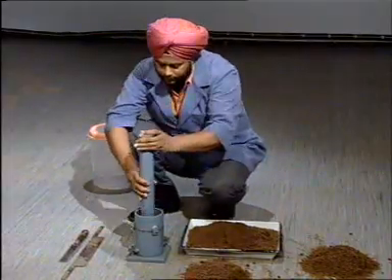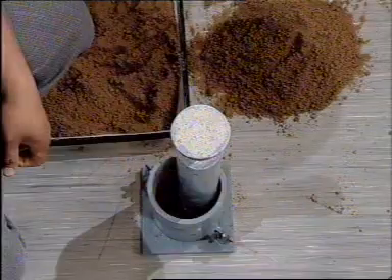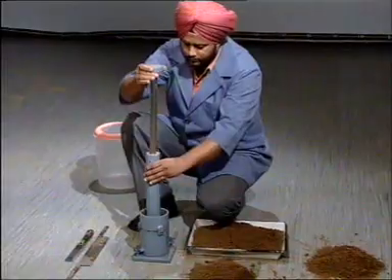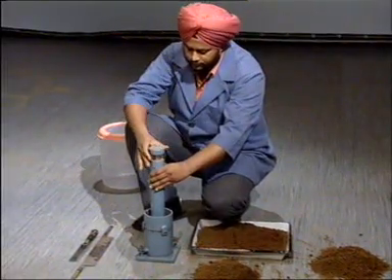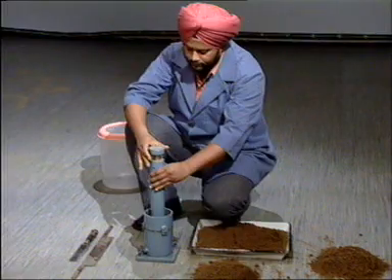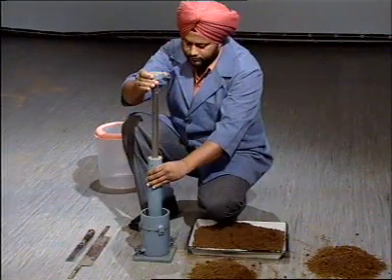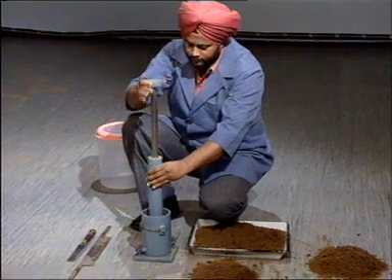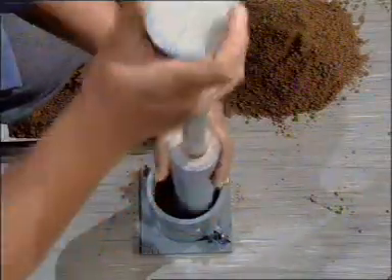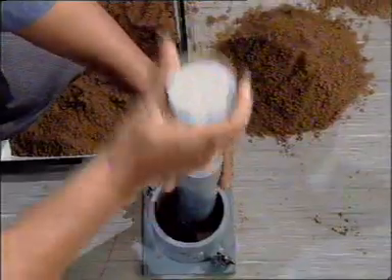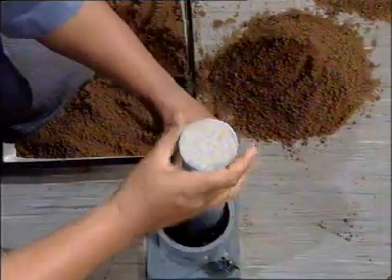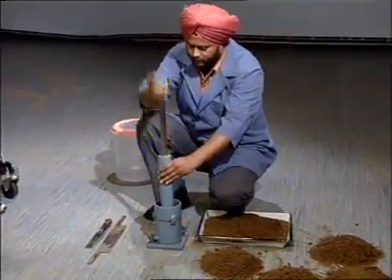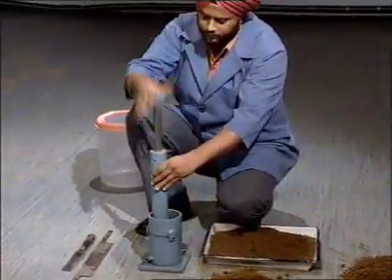Now place the tamping face of the rammer on the soil surface in the mold. Lift the rammer fully and drop it freely. This imparts one blow to the soil. Ensure that the free fall of the rammer should be 31 cm. Continue giving blows by lifting and releasing the hammer by shifting the position on the soil surface. Compact the layer by giving 25 blows of the rammer.